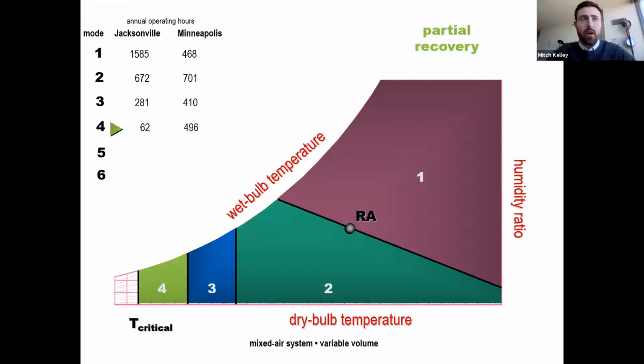So typically, if you had economizer mode running, you wouldn't have a good use for that energy recovery wheel unless you were in the heating dominant season. And even then, I really don't think that it would be a good use of fan energy to be using that energy wheel, because often, even in the heating season, you would then overheat that supply air temperature, and you'd need more mechanical cooling to cool it down. So typically when you're in economizer mode, you wouldn't be using that wheel at all. So I apologize if there was a discrepancy in the earlier slides.